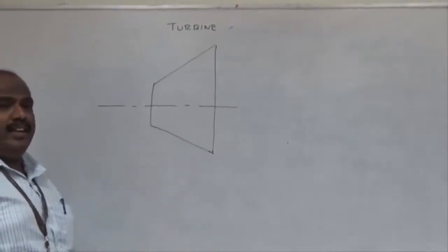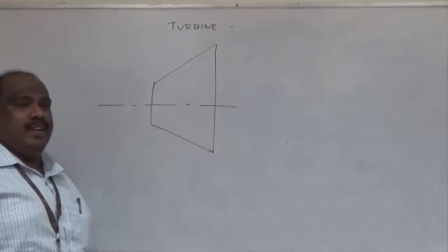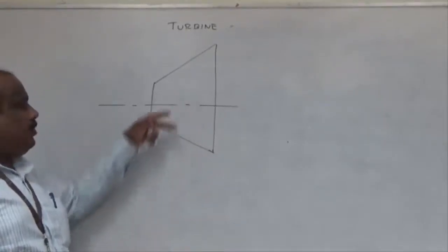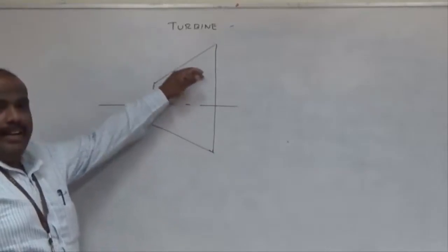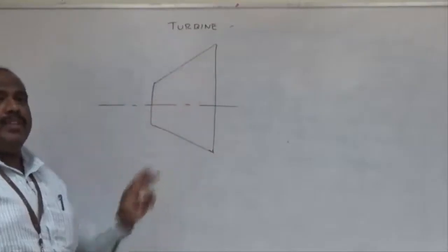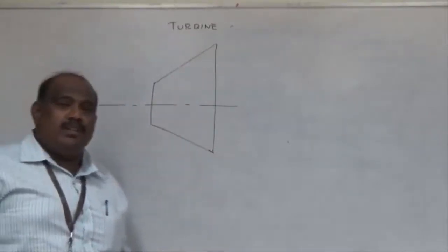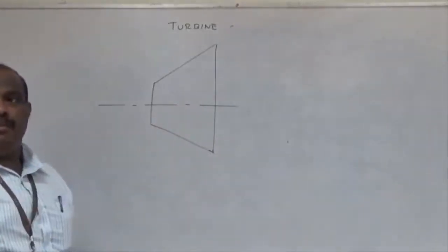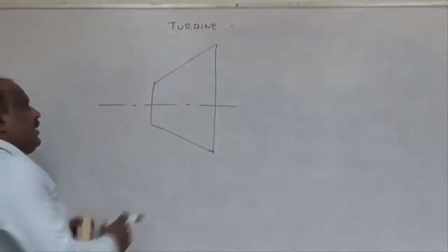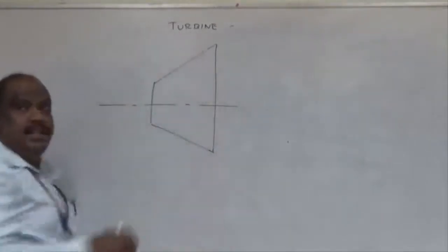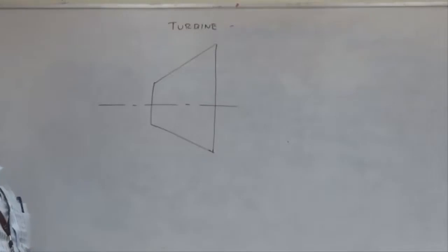So what are the other differences between the turbine and diffuser? Yes, the blades. Even though we are drawing the same diagram for both diffuser and turbine, in case of turbine we have rotating components, moving blades. In diffuser there is nothing like that; it's only because of geometry. Here not only the geometry, but the impact of blade is also important. So even though I am drawing a turbine like this, in your mind you have to imagine there are rotating components inside this one. And definitely the turbine should produce power.